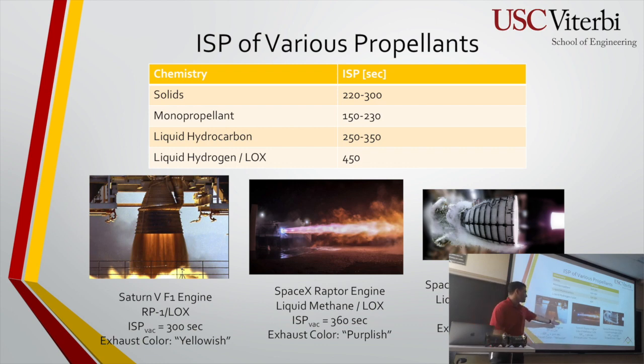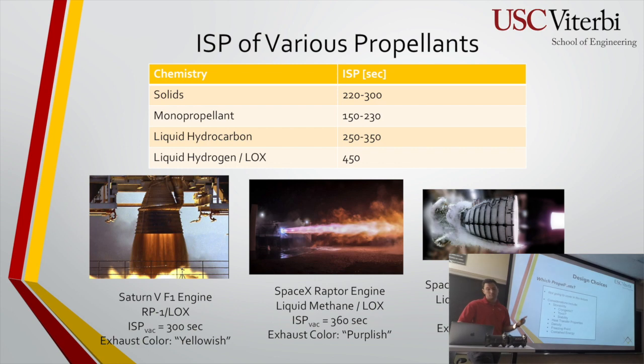So for instance, with SpaceX, other than the whole thing that methane's on Mars, and other than it being cryo, is there another reason why you think liquid hydrogen isn't used all the time? It's light, right? So it's really light, and that means if you want a ton of it, you need a huge tank. It has the lowest molecular weight. Then all of a sudden your tanks are big, and you have a ton of mass, and if you go back to the original rocket equation, where it's the final mass over the initial mass, then it ends up being all right. It's maybe not the best.